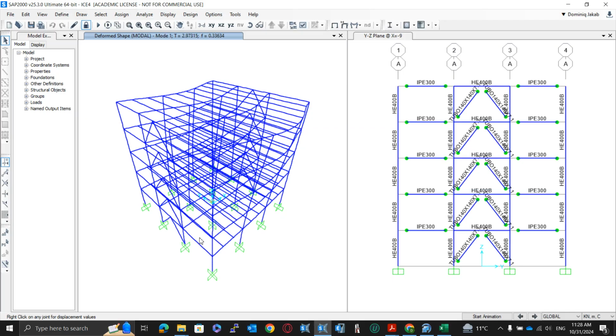One key element here that we have not assigned is the diaphragm constraint, in Romanian, efect de șaibă rigid. Now this helps us transmit the load to the slab, to the floor. That's very important.